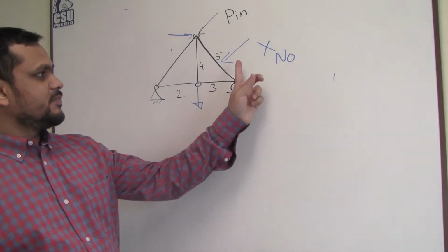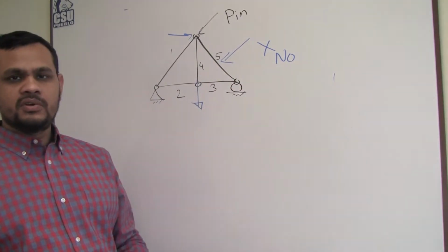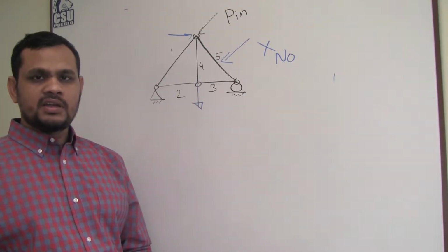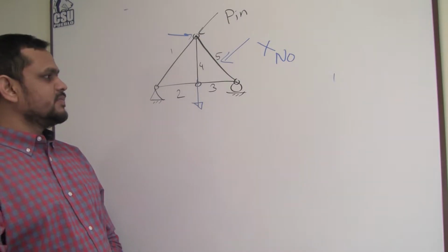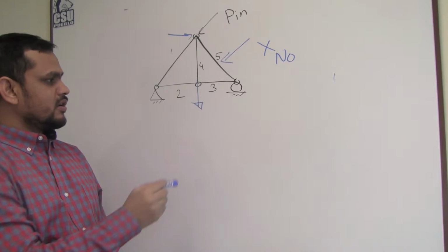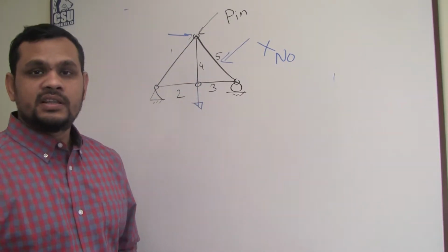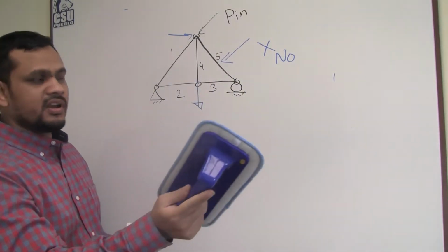Now what happens if we apply load in the member? Then it will be frame. Moment will develop in the member. So that must be solved using frame analysis. So all the theory for truss is valid if all the joints are pin and loads are only at the joints. In classes you learn that we can solve truss in 2 ways, or somebody learn 3 ways.